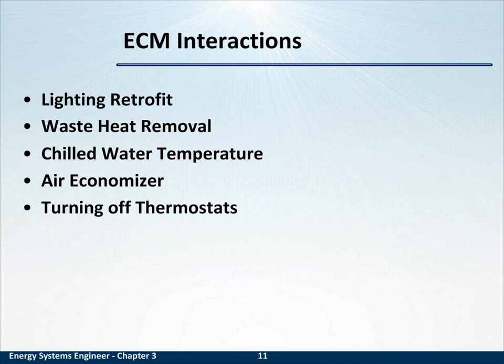Let's consider an unintended system consequence when you achieve energy conservation in your operation or in your customer's operation through lighting retrofit, the ECM interaction. The energy conservation measure of lighting retrofit. If you replace incandescent lighting with lights that are more efficient, likely they convert less of the energy into heat. You now have lighting that generates less heat. During a cooling cycle, that's a benefit. During a heating cycle, that's a disadvantage.